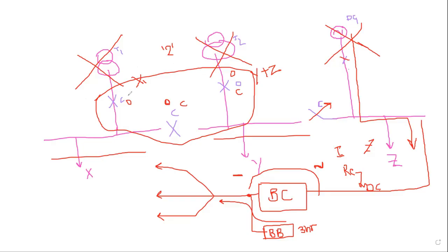For 3 breakers, we have 2 keys. If I insert a key here and a key here, then this will work and this will be open only. If I want this, I will remove this key and place it here. In that way, we can do mechanical interlocks.